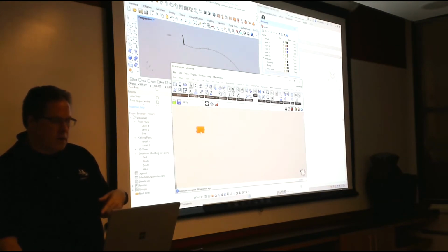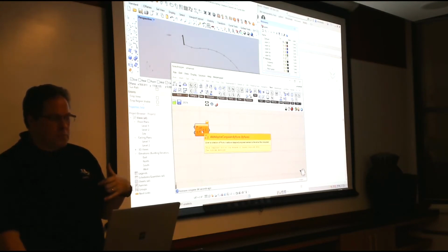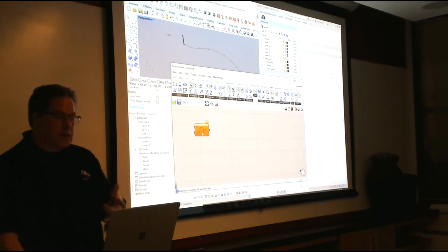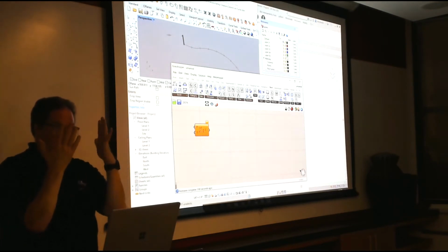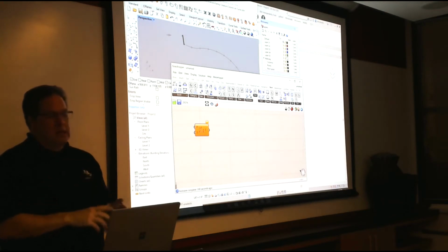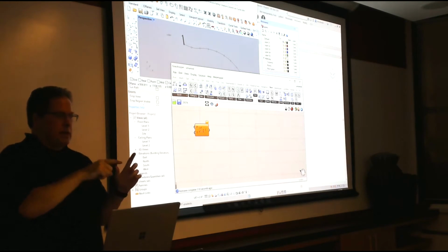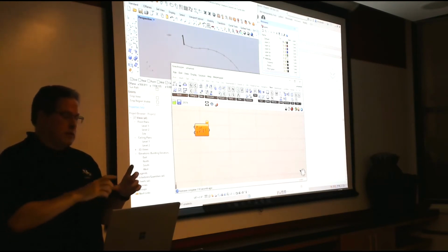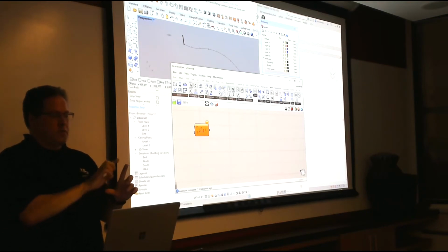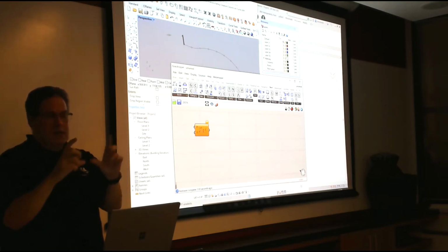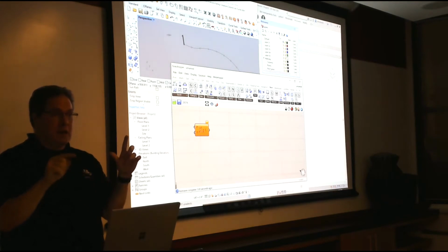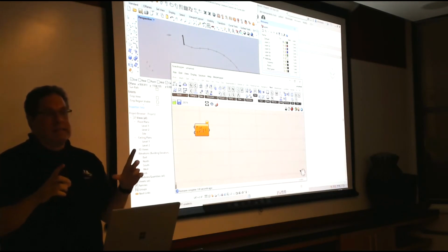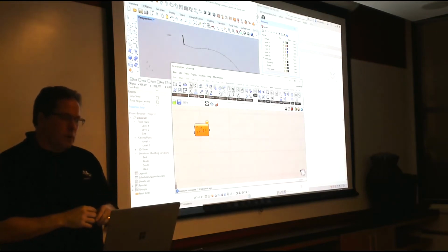So if we have an adaptive component, we throw the points in there and the type, and it'll create the adaptive components. Now, the cool part about this is because we have Grasshopper running, we could use paneling tools to find all the points. For instance, we don't have to make the perfect untrimmed surface in Revit to analyze them. We just get our points, and we can have Grasshopper just place all the adaptive components. Another cool part is that Grasshopper is smart enough to figure out, well, this is a full 4-point frame, so I'm going to put this one. And on the edges, I have other conditions, so Grasshopper could put different adaptive components at different parts of the edges on the fly. So you can drive that through Grasshopper if you want, and that works really well.